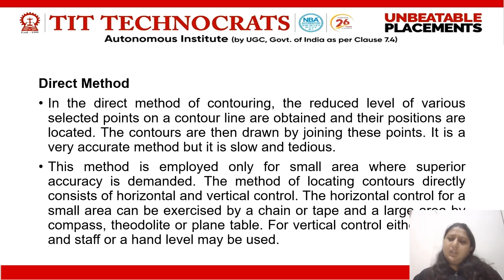How? The entire work of contouring is done on the field itself in the direct method. I'll find out different points, their locations and their RLs. After knowing the RLs of different points, I'll draw the contour lines there itself. Hence, for this method, we need a large amount of time and more accuracy, and it is not possible for major projects, but it is possible for smaller areas where we need very fine details or superior accuracy.